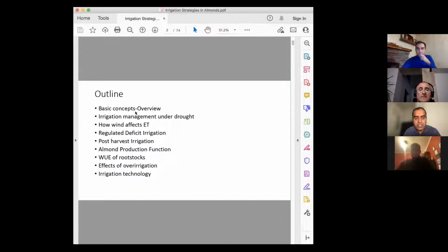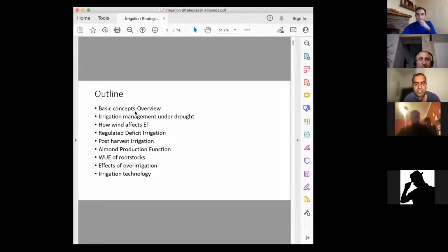We'll talk about irrigation management under drought, regulated deficit irrigation. We'll talk about post-harvest irrigation. I'll also talk a little bit about almond production function studies done here in California, and then water use efficiency of different rootstocks. We'll talk in detail about effects of over irrigation, and then a little bit about irrigation technology.